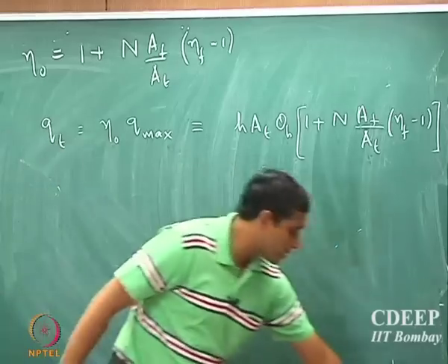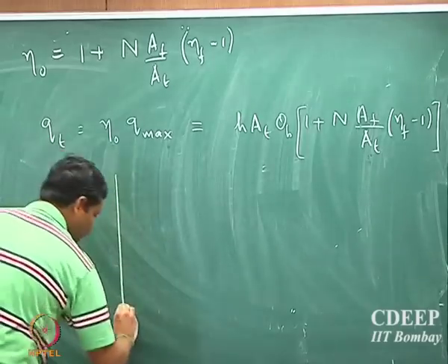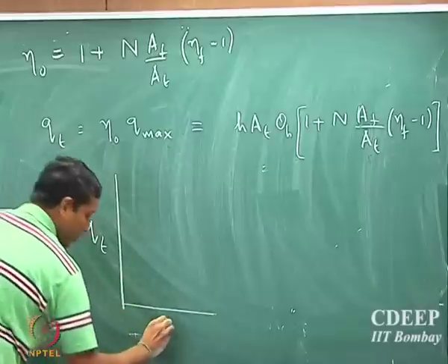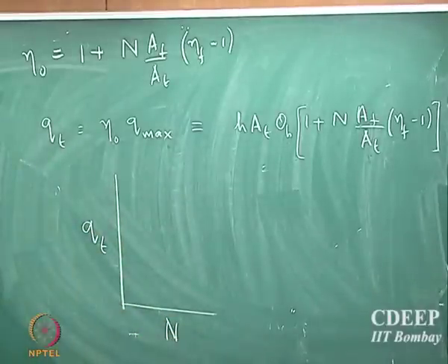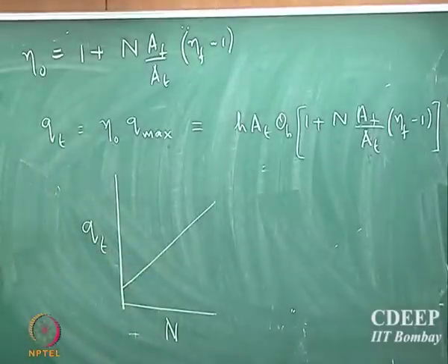So for any specific system, the first thing you should do is, as you increase the heat transfer area by including multiple fins, make a plot of Qt versus the number of fins. Only if Qt is going to increase with the number of fins is it worthwhile making such a construction. Otherwise it doesn't make any sense. It may not be linear, but a simplistic case is that Qt increases linearly with the number of fins you construct in this complex system; only then is it worthwhile to put them in.